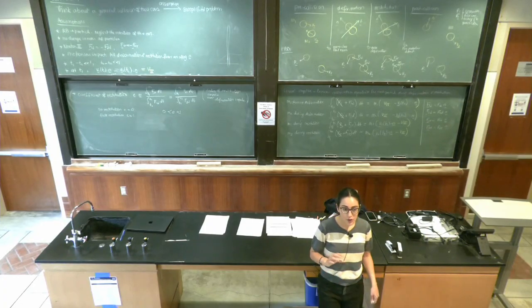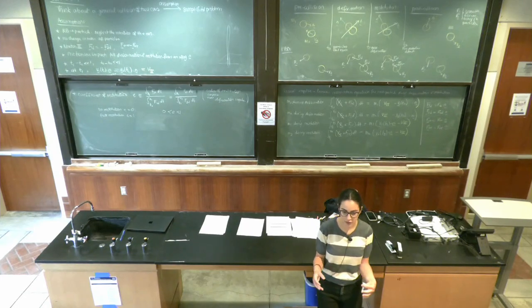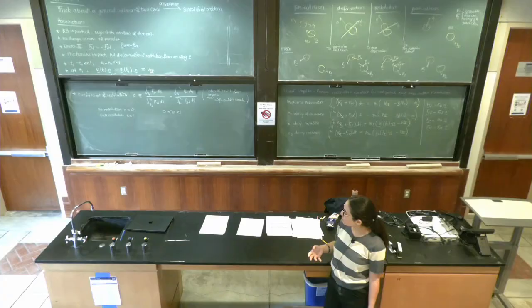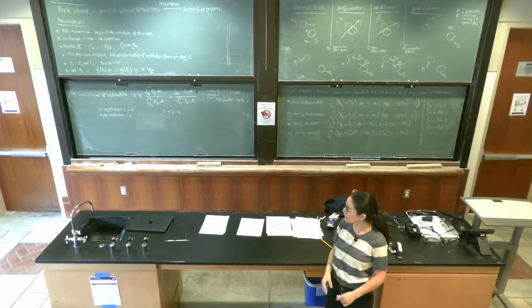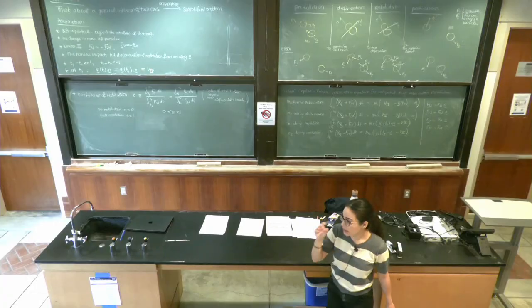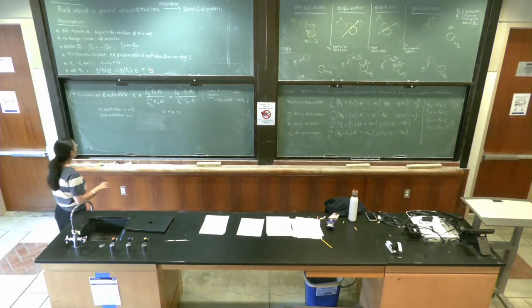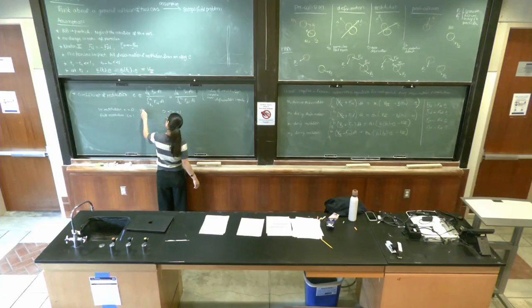So E is a number that encodes the magnitude of the restitution, the permanent deformation. If E is equal to 0, all the deformation is permanent. If E equals 1, it's not permanent at all. That's why when E is equal to 0, we call that the plastic case versus the elastic case.